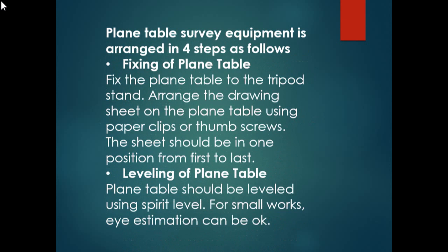In the fixing of the plain table, fix the plain table to the tripod stand. Arrange the drawing sheet on the plain table using paper clips or thumb screws. The sheet should be in one position from first to last. It should not shake.